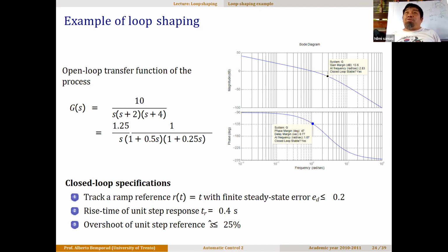Because when you choose its auto tune, you don't know what its considerations were for taking KP, KI and KD. You have the values, but you don't know why it chose that gain. MATLAB will not tell you why this KP, why this KI, why this KD. Because what I want, when you use visual tuning, is why you took this KP, this KI, this KD. It is not this. It's not the answer that I'm looking for. I'm looking for the reason why you choose certain things.